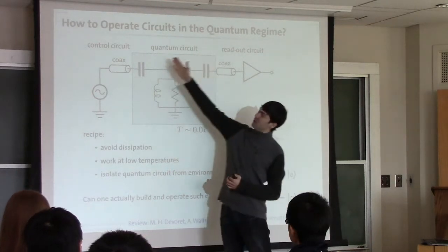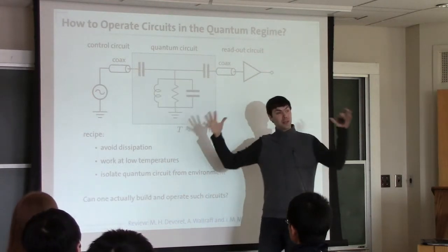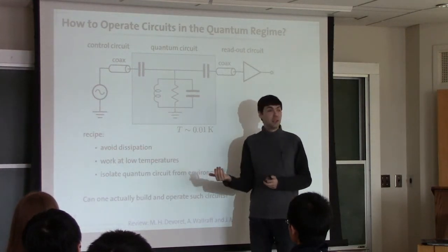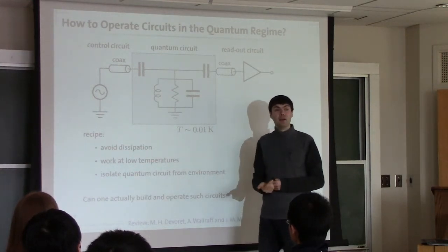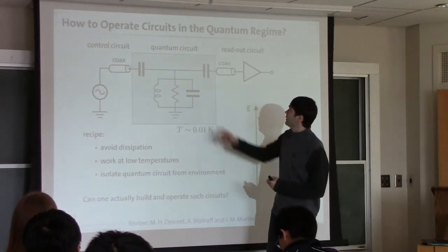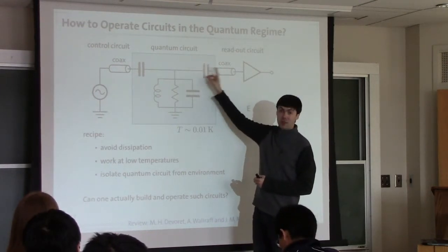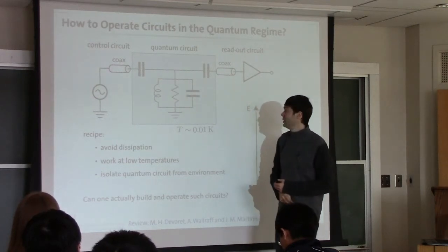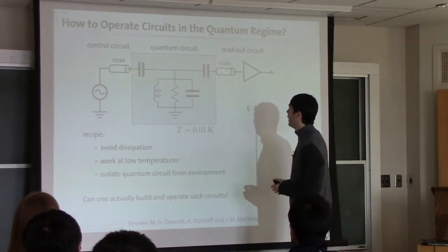So there is this schematic box, which when you are in the box, you're protected. The box can be a metal shield, a magnetic shield, filters in the lines. You can put capacitors to avoid direct coupling through the wires that you send to the circuit.